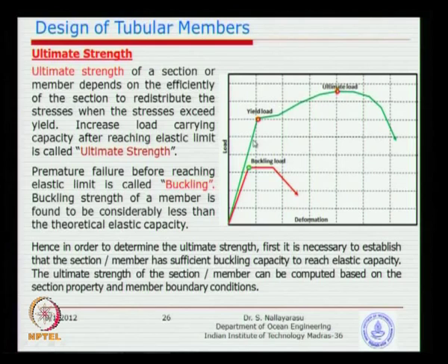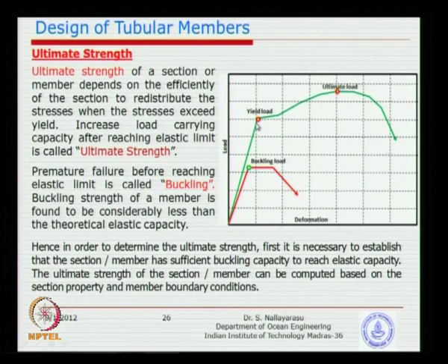Whereas if you take the same column, apply the same load, but make the cross section smaller, it becomes too slender even before it achieves the full yield. Yielding means the Fy. The column starts buckling laterally or buckling locally and starts failing earlier. Now we can decide what we want to do. You might have thought that by reducing the size of the structure I have economized.